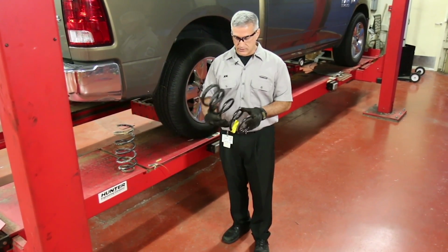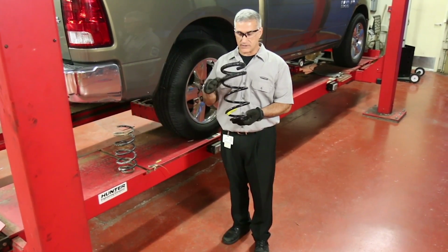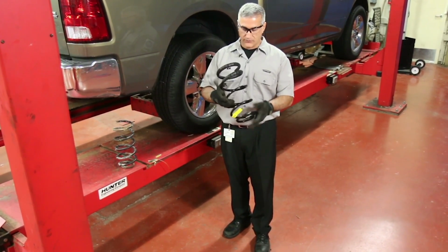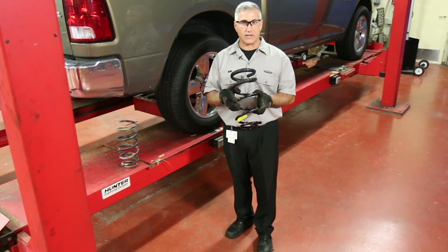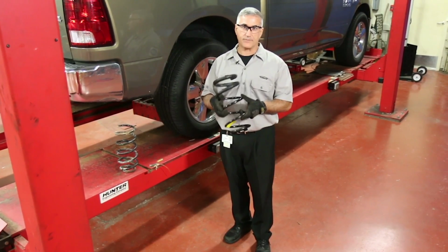During service, the technician should remember to grab as many coils as possible when compressing a spring and leaving gaps between the coils. If you only grab a few coils in the middle and you compress them completely together, that can cause the spring to kink or be damaged.